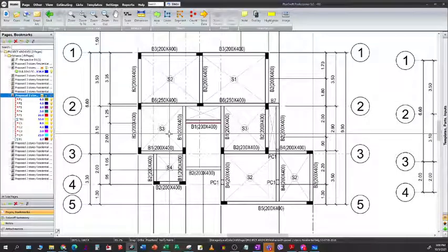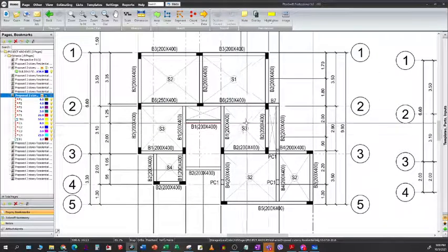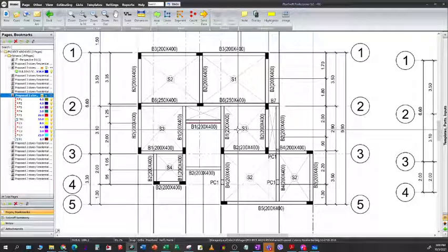Now, why are we doing this? It's because, especially if there are really large areas that you are going to estimate, it may be very hard for you to account for all those slabs. So what we do here is we just analyze one slab and use ratio and proportion to account for all the similar slabs. So we take one slab 1, one slab 2, and probably one slab 3, and that will represent all the other areas where those slabs can be found.